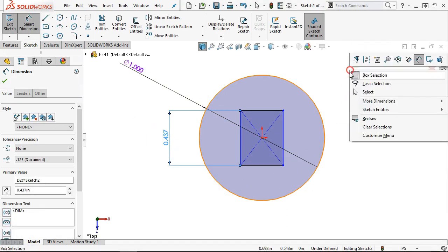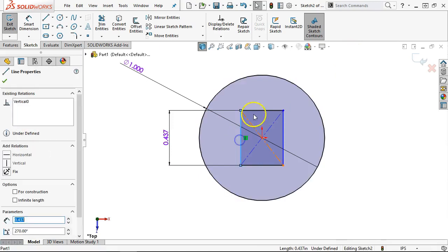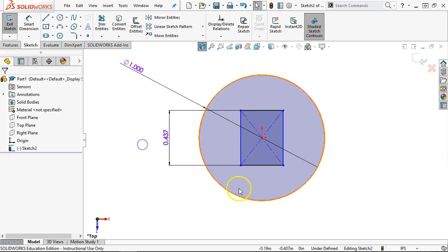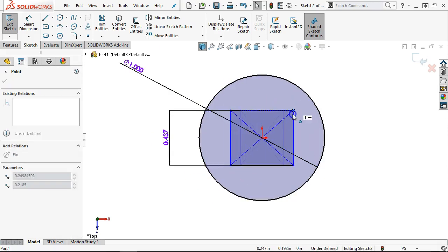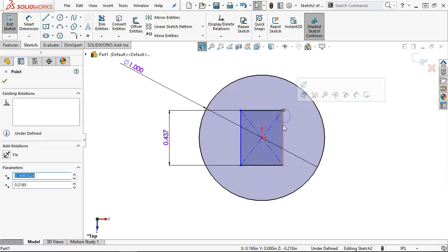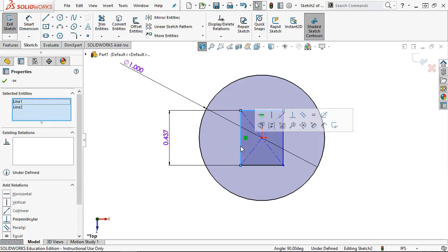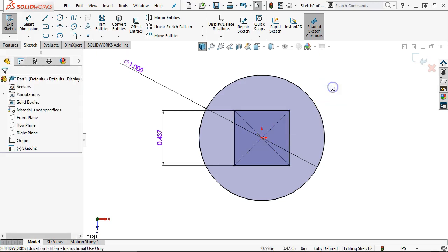All right, so 0.437, so 7/16 rounded down. This is always going to be square, so I'm going to do the select, control, select. Right, so right now the sides are in blue. So when I pick any of the other two sides, select with the left button, hold down the control button, select with the left button again, and we're going to set those to equal on the pop-up. And over on the lower left, right about where my timer is, also the other equal.